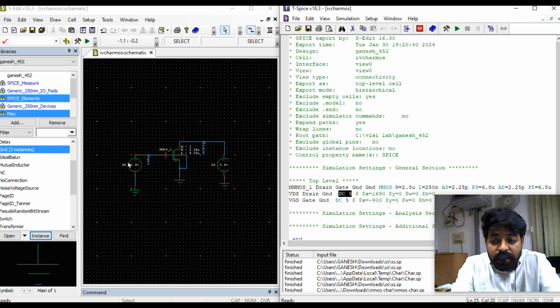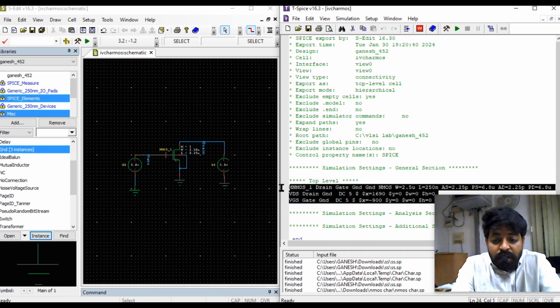And in a similar fashion, there is GS, the voltage source. V is the notation, directly it will be added, even though you give the name of GS for the voltage source. That voltage source has the notation of adding the V over there. So the voltage source with the name of VGS, right, is created between the gate wire or gate node and the ground, with the strength of 5 volts. So this is called a spice netlist for the designed circuit.